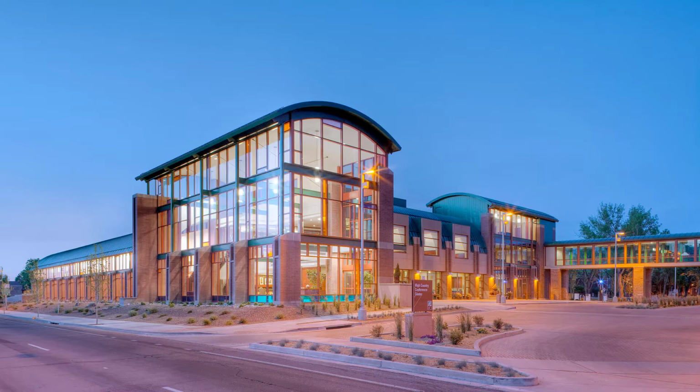And so we had to come in after those columns were built and measure the distance between those columns so that we could build the glass and glazing that went in between them to the exact right dimension. If we hadn't done that, we might have had bigger gaps for the caulking. That might have been out of the caulking specification in between the mullions of the glass and the masonry columns.